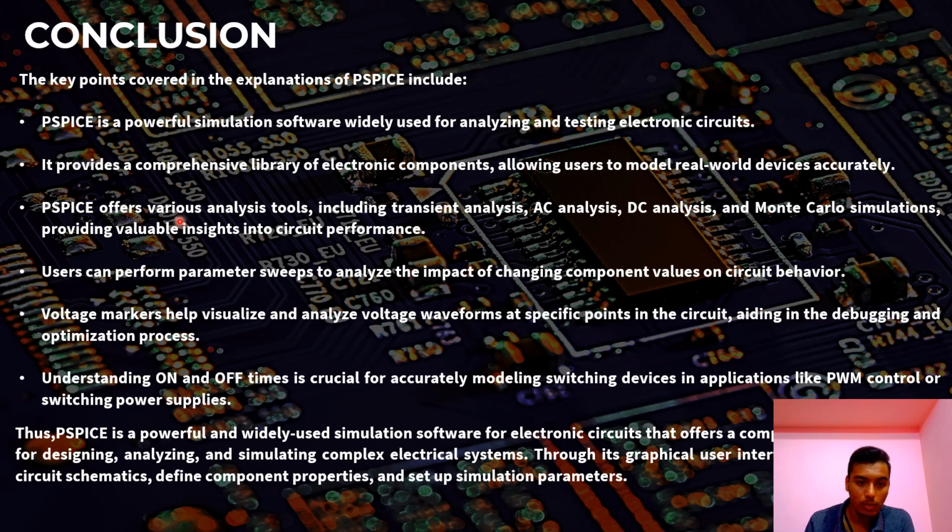Then it offers various analysis tools including transient analysis, AC analysis, DC analysis, and Monte Carlo simulation, providing valuable insights into circuit performance. Users can perform parameter sweeps to analyze the impact of changing component values on circuit behavior.